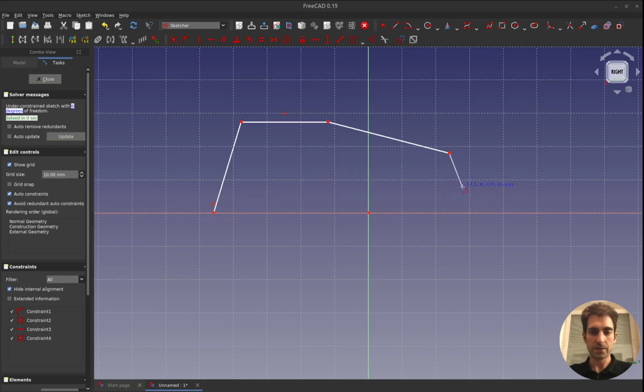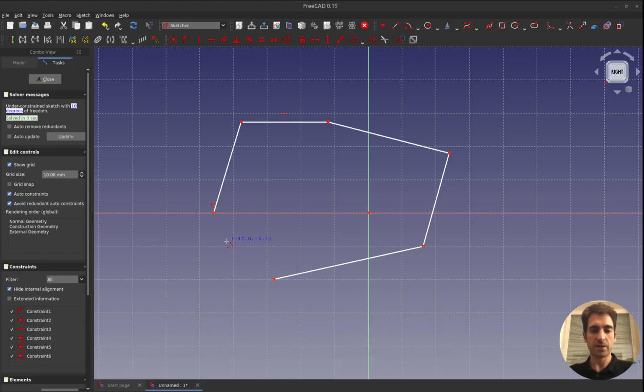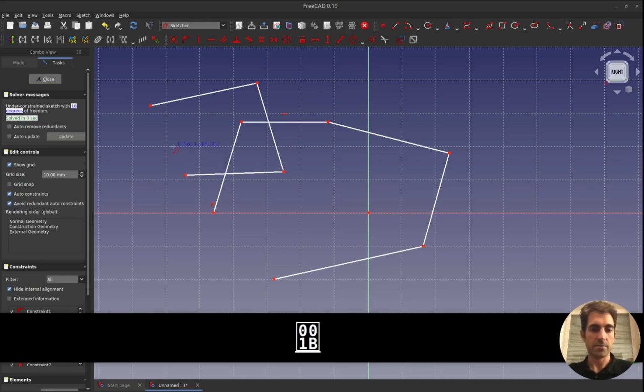If I'm done, I can do a couple of these kinds of lines. Then I can go out by hitting the escape button. So this is the escape button. It is showing me something funny, but this is how it shows. The escape button is technically breaking and stopping this multiline. If I want to do it again, I can immediately start doing the same again, because the last command that I used is still on the mouse, as you see. If I want to get rid of it, I can use escape.